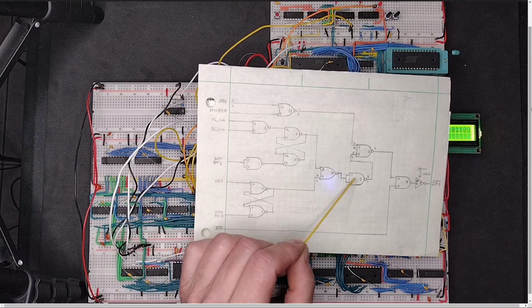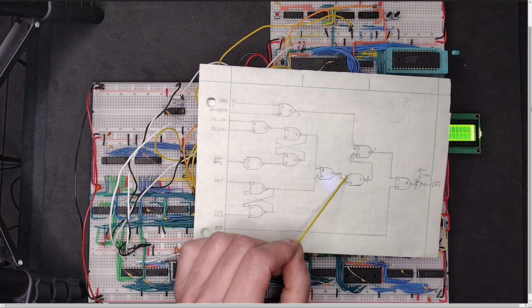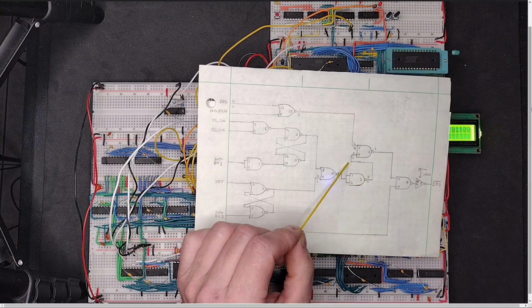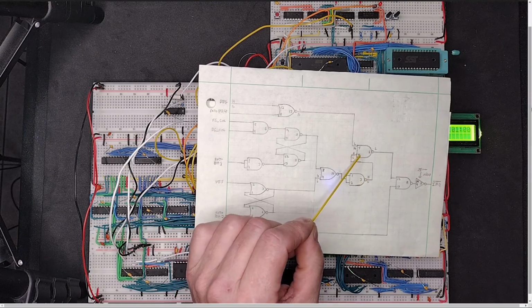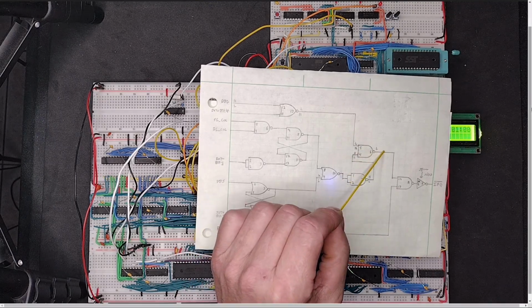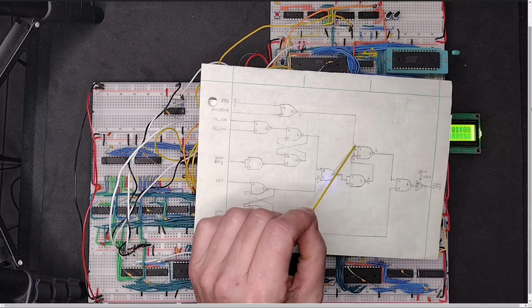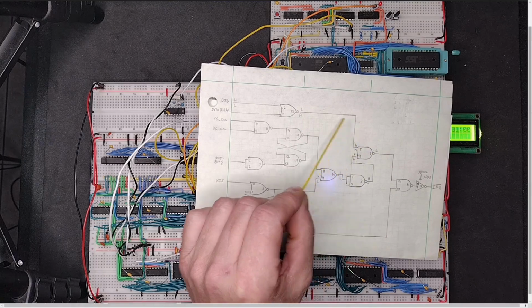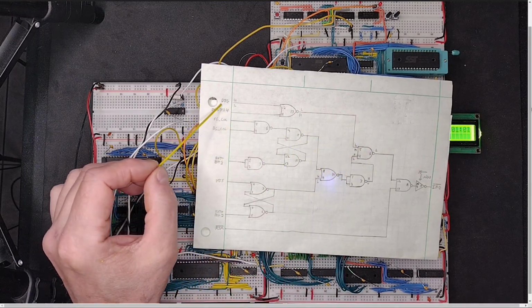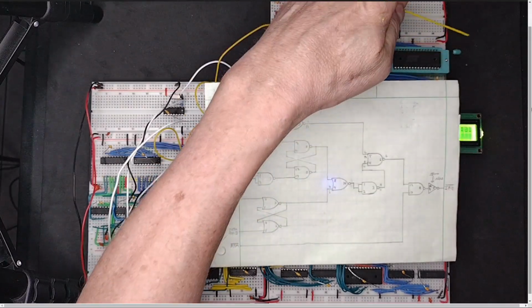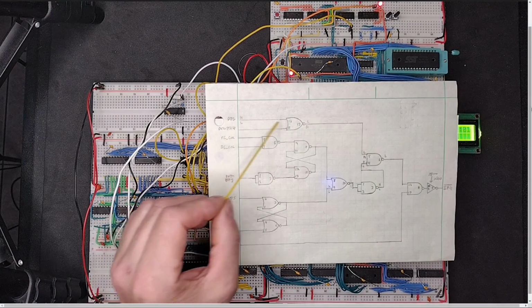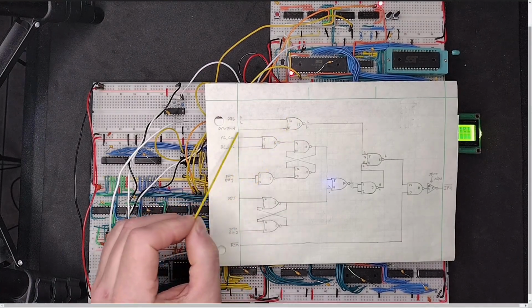It goes through this NAND gate, which I'm using as an inverter by tying the two inputs together. So this is low, so this will go high. And since this is high, then this will go low only if this output is also high. When is this output high? Well, here's how I do the disabling. I have the debug signal, and when I'm in debugger mode, I have that wired up so that it goes into one input of this NOR gate.